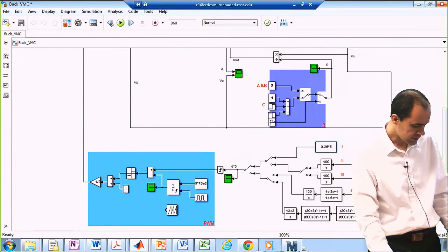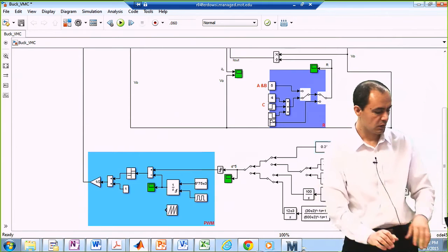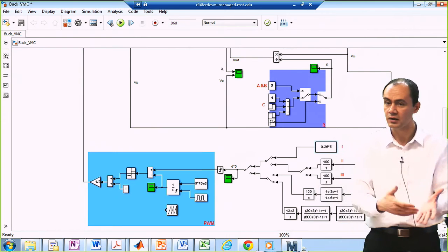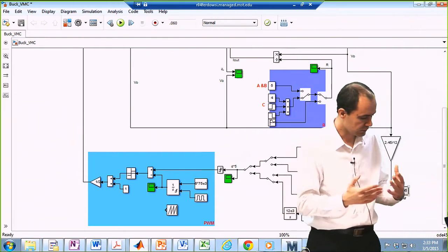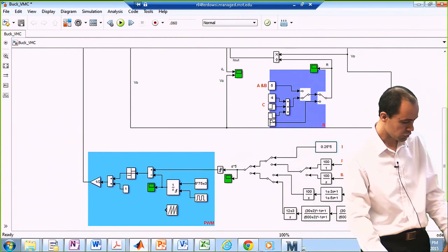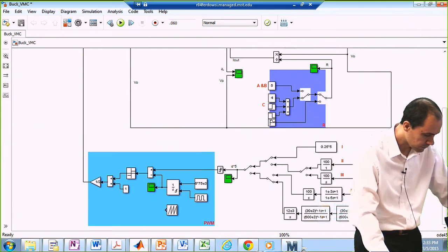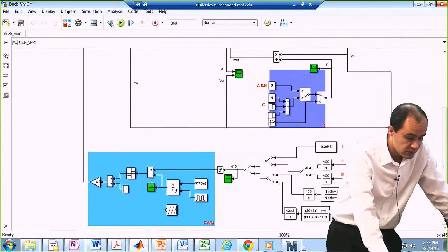All right. As far as the measurement of the output voltage is concerned, this is my output voltage. I just have a simple gain. My output voltage is supposed to be 12. The reference available to me from the chip that I have purchased is a weird number of 2.45. I've intentionally put this weird number over here. So you're looking at a very simple gain of 2.45 divided by 12. All right. And we compare them against each other, and the rest is the compensation network.